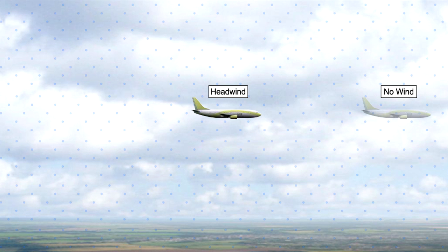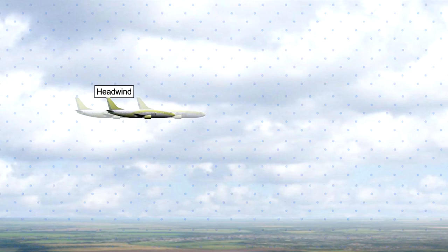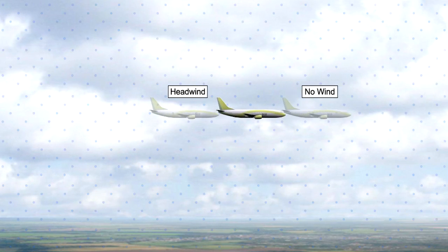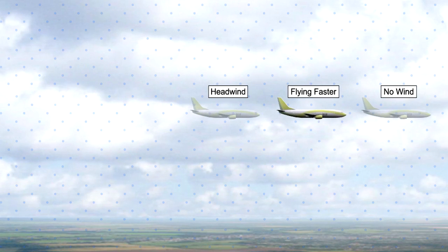In order to minimize this effect, the speed of the airplane is increased by a margin slightly less than the amount of the headwind. The increase in speed will increase the thrust and the power required, and therefore the fuel consumption. But on a positive side, the aeroplane will be exposed to the headwind for a shorter time period if it is flying faster. This higher speed then recovers some of the range lost caused by the headwind.